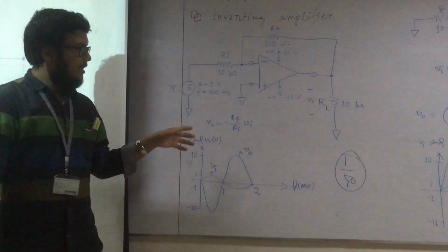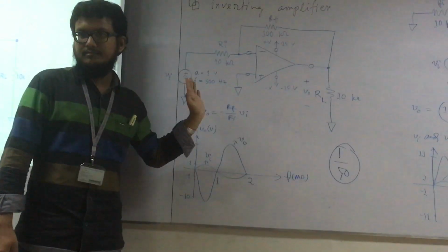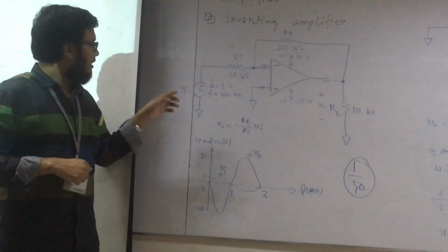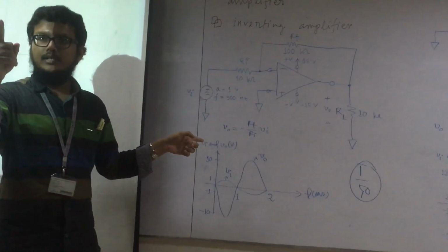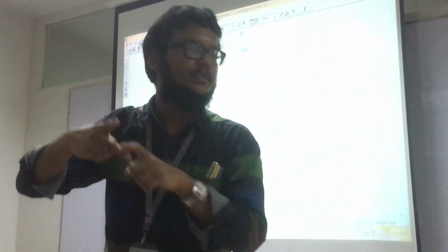Well, you need to see, okay, doing transient means getting the x-axis, not the y. On y you need two items. How do you tell that? By attaching markers. These are voltages. You need voltage markers. Two voltage markers are there, one for nodal voltages, one for non-nodal voltages.